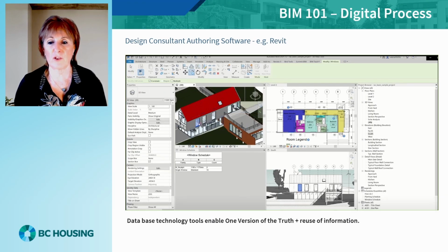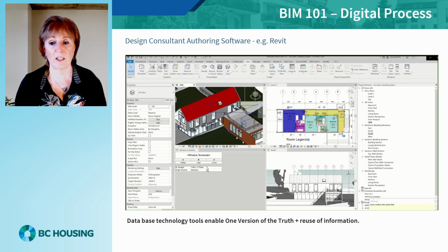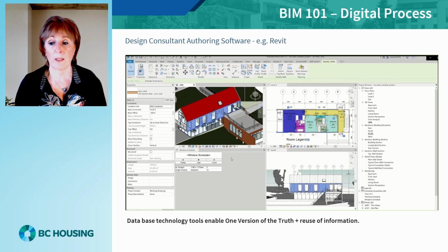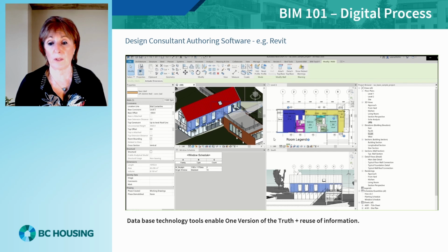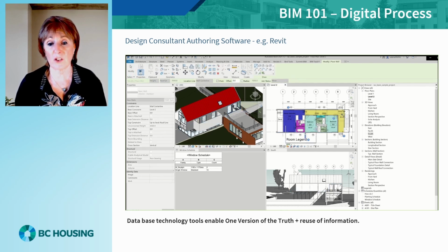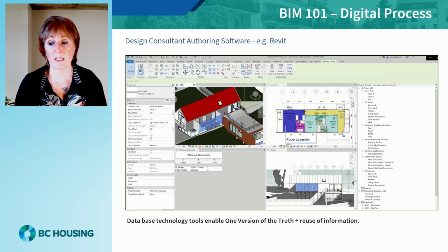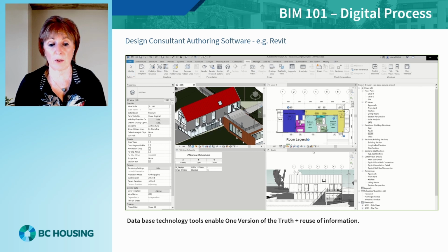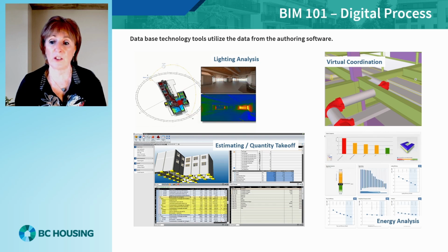This digital, data-driven process is enabled by the use of data-driven software. Rather than creating drawings, data is entered into a software, like Revit, database, and a complex query run to generate the drawing views. This approach, using data to drive the process, means you change something once, and as you can see in the video, every view updates. This leads to the concept of one version of the truth. It is this data set that other software solutions can then utilize.